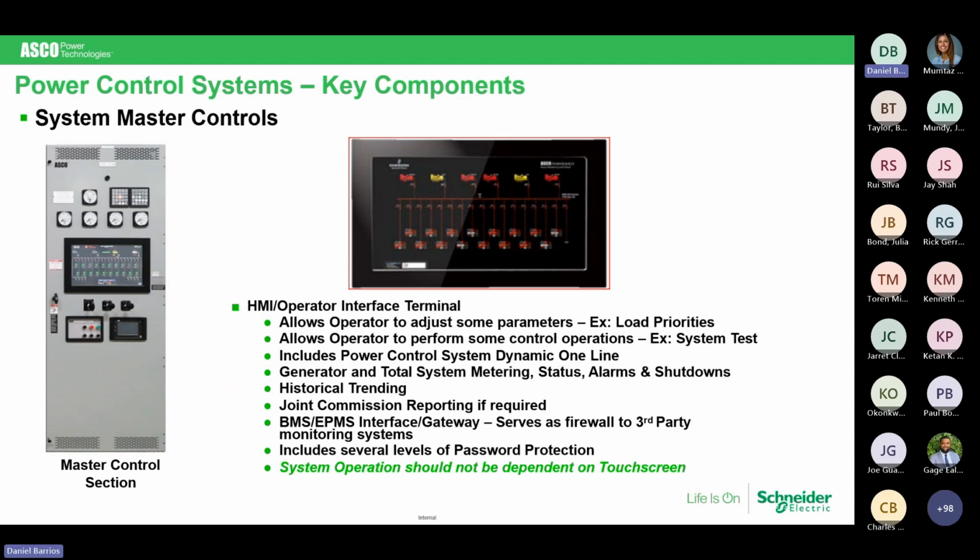The master PLC is a key component. HMI is a human machine interface. OIT, operator interface terminal or such. This allows you to adjust some parameters. You know, that's very important. You don't want to have to call a tech out just maybe to set a timer from 5 minutes to 15 minutes or so. All of those types of parameters that you can do in the field yourself are password protected, but we can give you a list of those, okay?